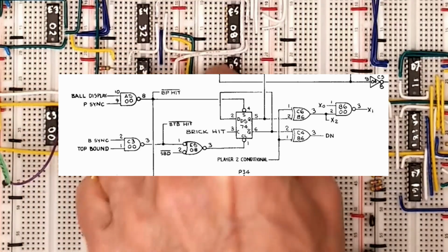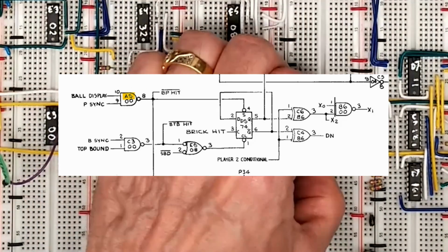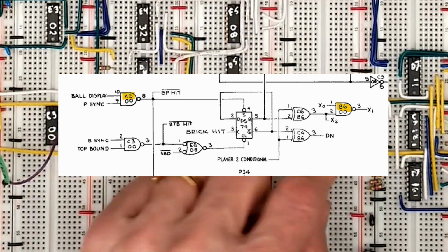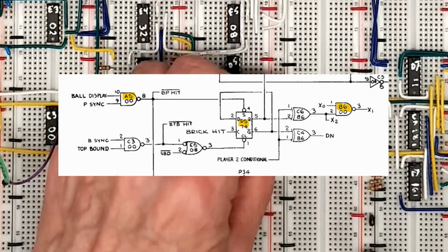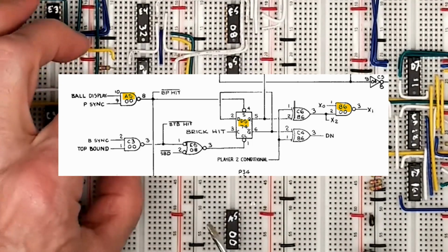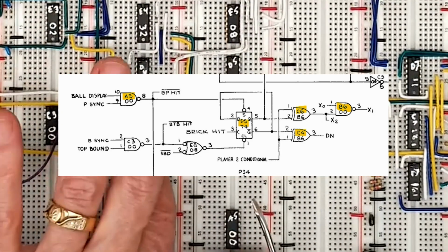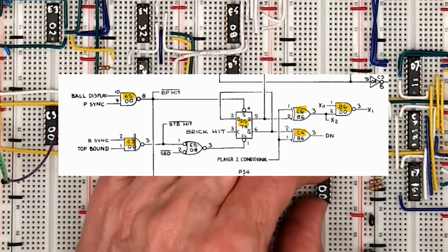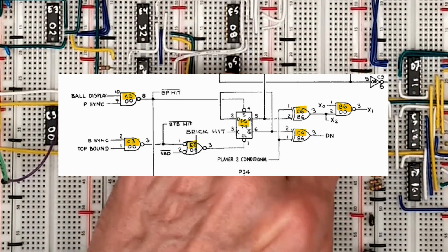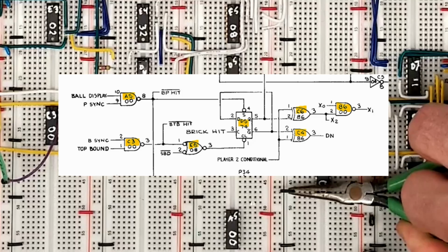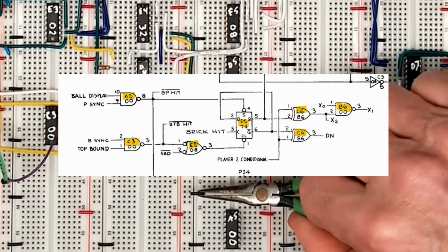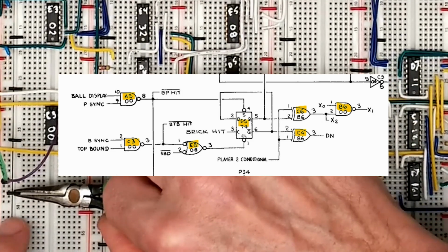We'll need new 7400s in Able 5 and Baker 6, a new 7474 in Dog 5, new 7486s in Charlie 6 and Charlie 4. We'll use a NAND gate from Charlie 3 and one more AND gate from Easy 5. This looks a lot like our own cheap X motion control with a few features.